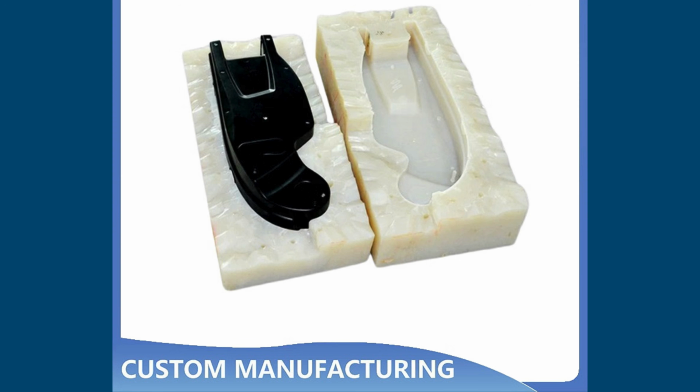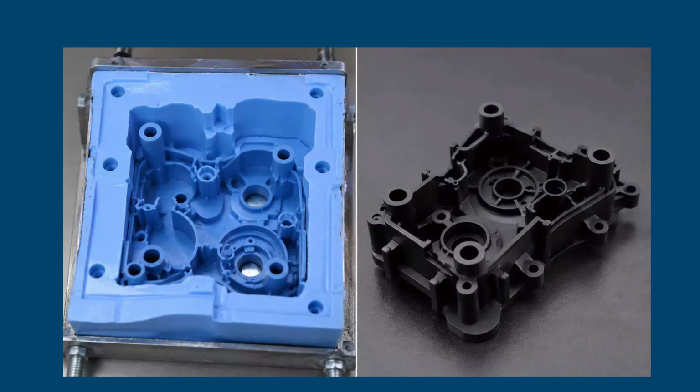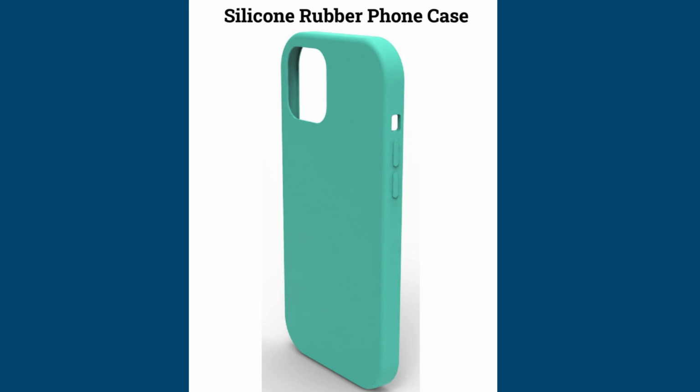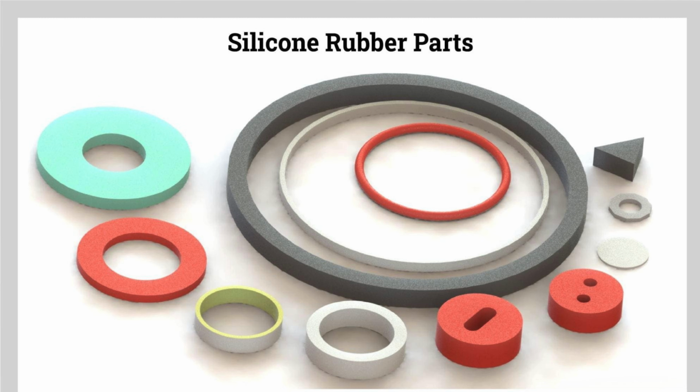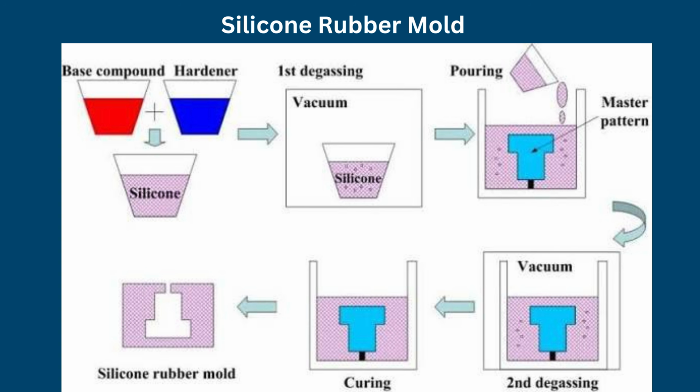applications. Silicone molding refers to a family of manufacturing processes in which elastomeric silicone materials are used either as the mold itself or as the molded product. Compared with conventional steel or aluminum molds used in injection molding, silicone molds are inexpensive, rapidly fabricated, and capable of reproducing exceptionally fine surface details. Consequently, silicone molding has become an indispensable technology for prototype development, customized manufacturing, and short production runs.